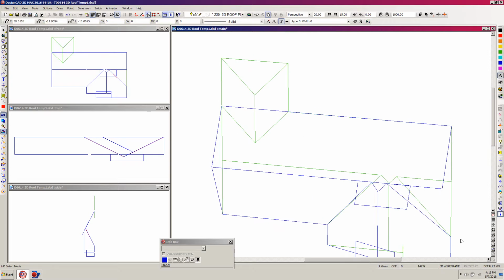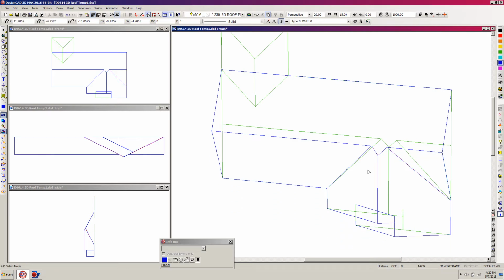And I need to draw this one in here too. So I'm going to turn blue and hit P, and we can get rid of our little nub plane there. We no longer need that. Select it and hit delete. So I do need to create a plane here to continue this primary plane here. So I'm hitting P for plane, right click, and right click. Oops, wrong place. Right click there, and then hit my scroll button. So I have those planes now.